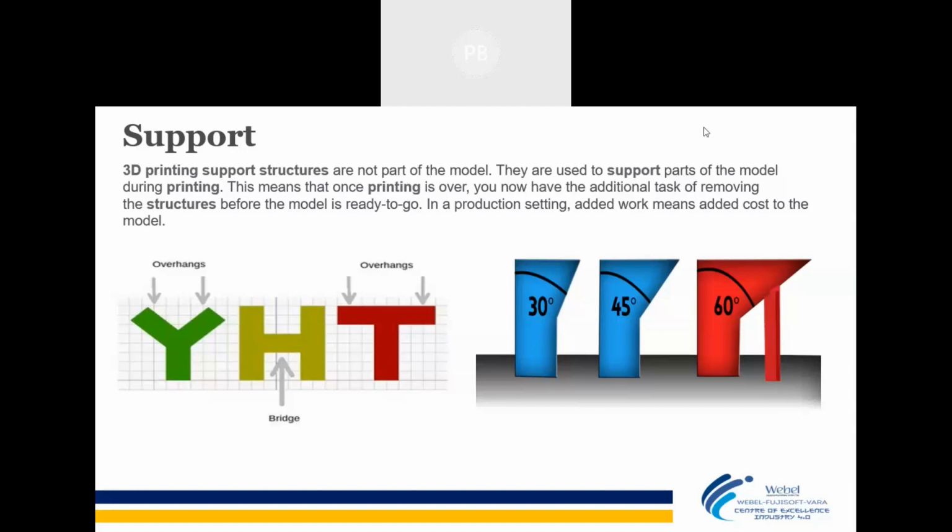So you remember these three basic terms. Tell me, which is more important? One is support, one is infill density, and another is layer height. Using these three parameters, we can change a lot of things with the 3D printer.